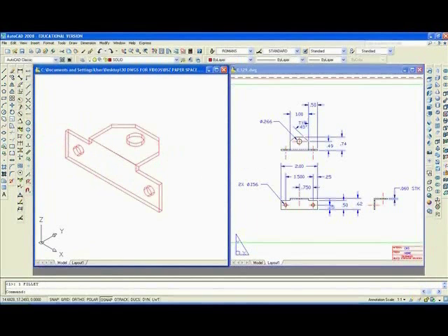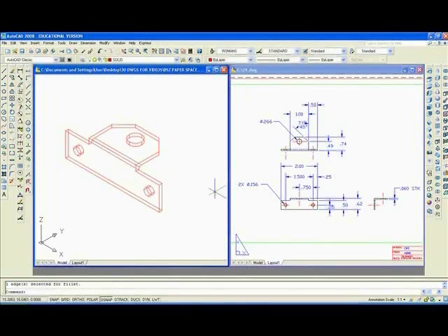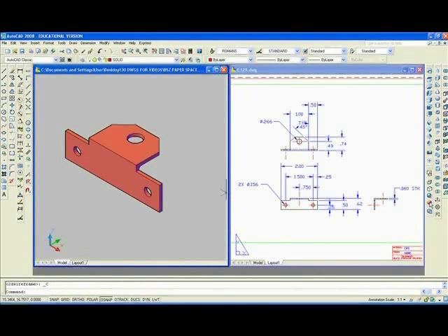To complete this particular part, we want to go to fillet, F, enter, and I want to fillet or put a radius on the outside of that point. So it says enter fillet radius 0.06, enter. It says select an edge. I already did, so I'll simply hit enter. And that, I believe, no, it didn't work.